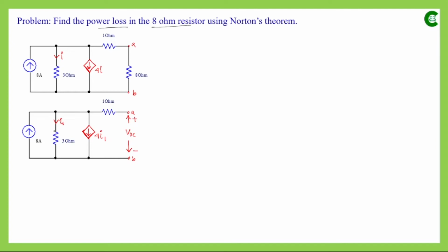So here as we can see, when this path is open and no current is flowing, we still have these 3 branches which are connected in parallel. So here we can easily apply the concept of KCL and find the voltage drop. Let's assume the potential of this principal node is V1, and the potential of this principal node, which has been assumed as the reference node, is 0 volt.